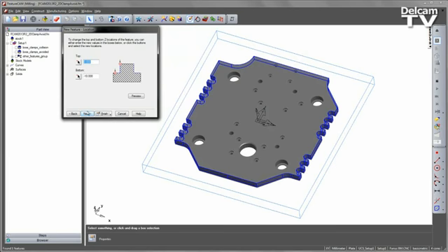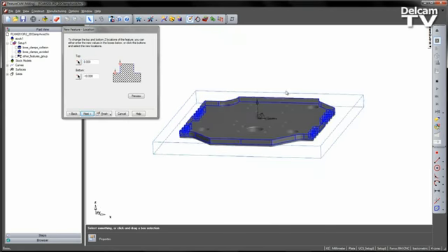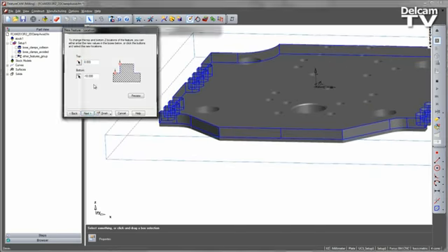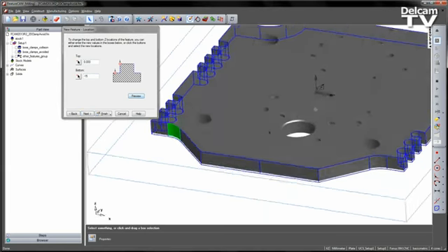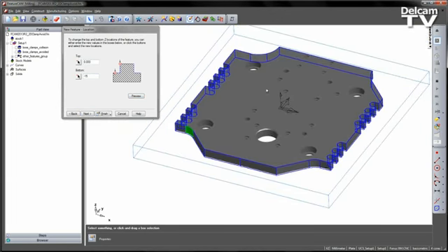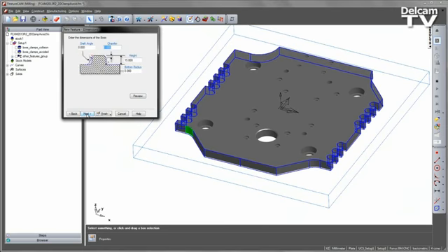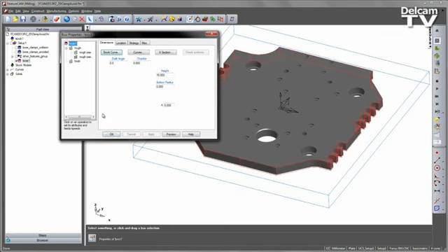I've already got my surface pre-selected, I just need the depth of my part. I can click to the bottom of the component. In this case I'm going to cut just past it by saying -15, so I add an extra bit of material or extra cut on the bottom. Everything else I can accept as default, and I'll accept the default tool choice as well and say Finish.